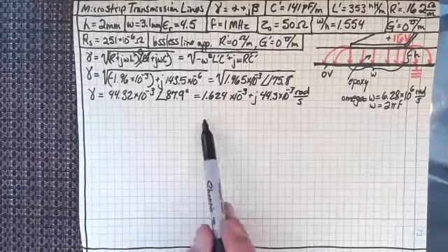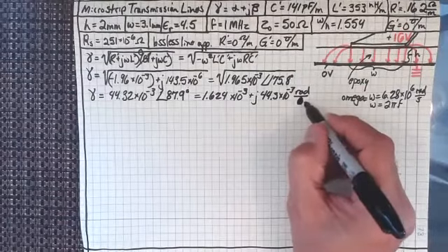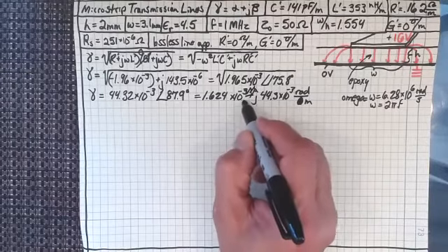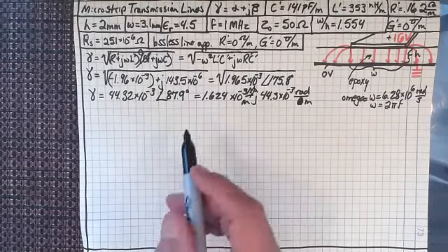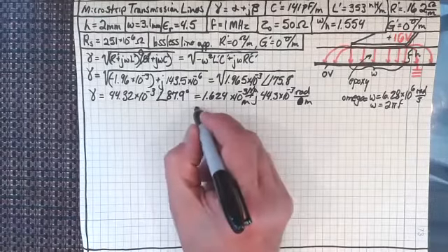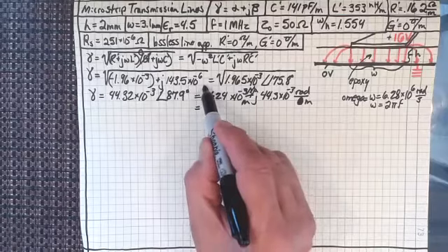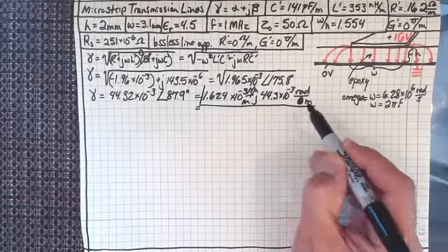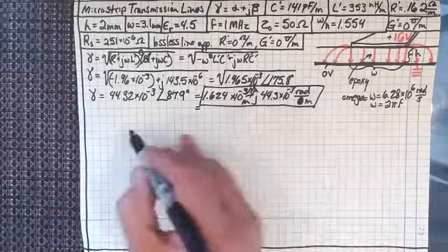Okay. Excuse me, not per second, per meter. And of course, this is in nepers per meter. I can change that to decibels per meter too, but it's really not going to matter too much. Let's remember that decibels are not really used in engineering equations. It's like degrees and radians, right? We have to use radians all the time, and we have to use nepers when we're working in mathematical equations like this.